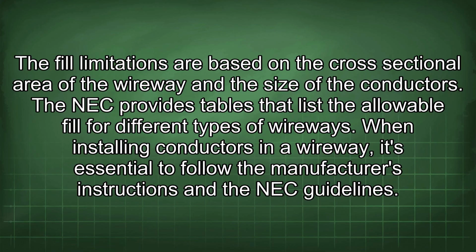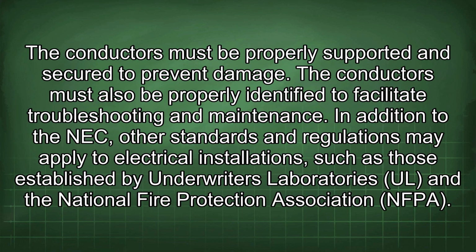When installing conductors in a wireway, it's essential to follow the manufacturer's instructions and the NEC guidelines. The conductors must be properly supported and secured to prevent damage. The conductors must also be properly identified to facilitate troubleshooting and maintenance.